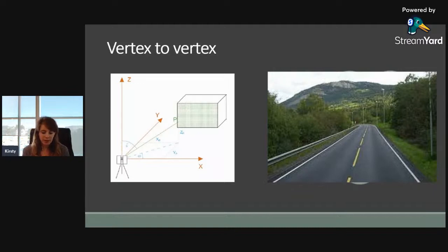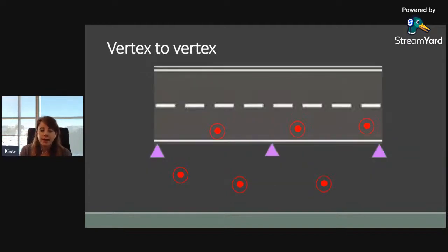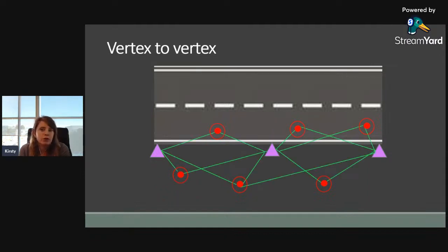And that's because of the belief that you've got the individual ground-based measurements that are measured on site, so they should be more inherently accurate than scaling it. So this is a problem when you're going beyond a kilometre and you can get 40 millimeters of error in those residuals. So for roading projects, you might want to let your scans fit to those targets and move around, so that if you've got really good total station control, you can fix those individual scans that way.